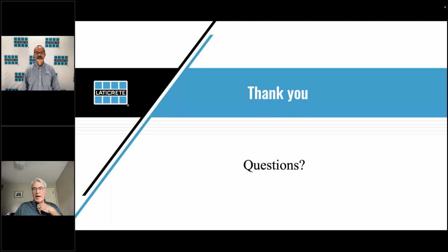All right. This one's from Adam. Since the system is not adhered, how will epoxy solve uplift? So if you're going to be doing an epoxy system, you're going to be epoxying the bases down also. So you'd be epoxying the base to your substrate. All right, good. Yeah, so if you're going to be using wind uplift, basically you're starting at your substrate, working your way up, adhering everything.